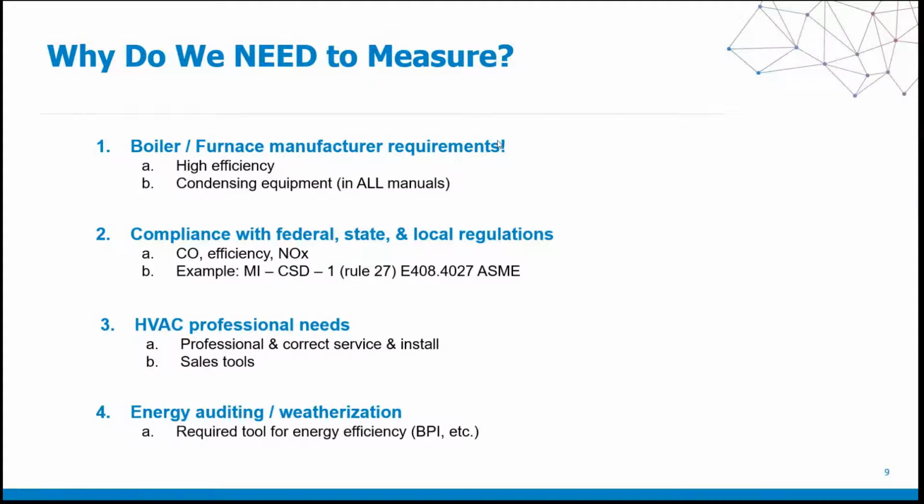Second is compliance with federal, state, and local regulations. We want to make sure that we're adhering to the regulations for CO, for the efficiency of that appliance, and also for NOx. And as far as HVAC professionals are concerned, it's our best foot forward. It is the best thing that we can do for our customer. It gives a complete service profile of the piece of equipment and provides confidence to the customer that they are actually utilizing their appliance correctly and that it's running safely the way that it was designed. And also, you can use your combustion analyzer as a sales tool. It can actually make you money through different diagnostic checks that you can do and for checking for cracked heat exchangers and some other things that I'll get into.